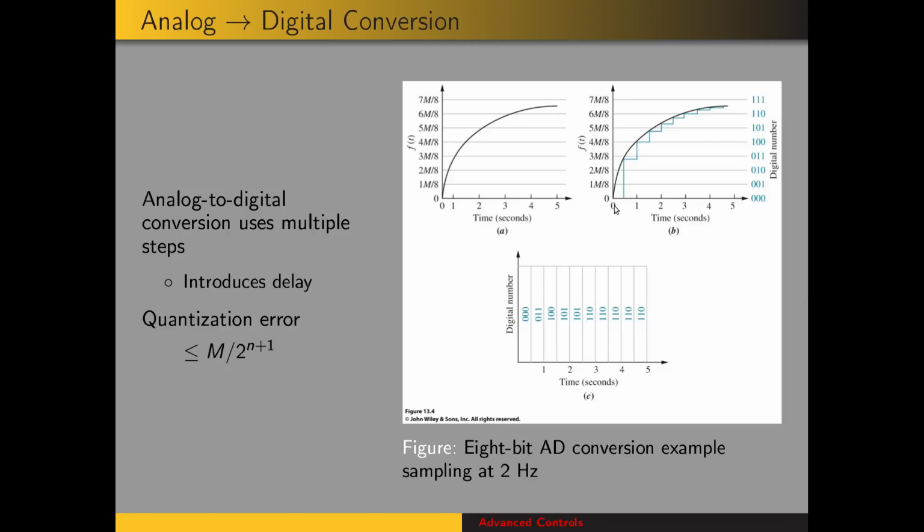So twice per second we're going to sample a new value. And what happens is that in this figure the value is sampled, and then that value is held until the next sampling interval. And then we sample it again and we hold that new value. So the conversion goes from the smooth curve to a stair-step looking curve.